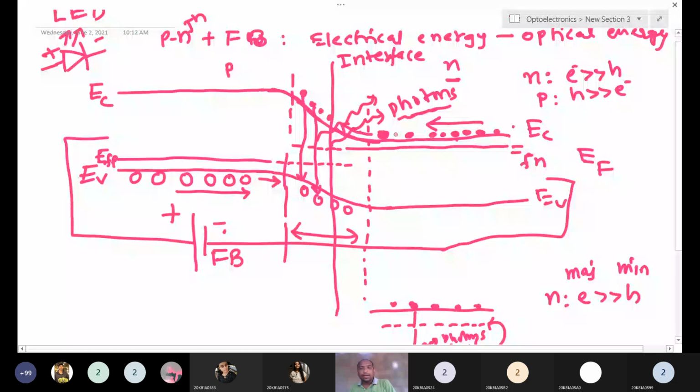If they do not cross the barrier, they will stay for some time in the depletion region. Meanwhile the lifetime of the charge carriers will complete, so they will recombine in the depletion region. Why are electrons and holes mainly recombining in the depletion region?